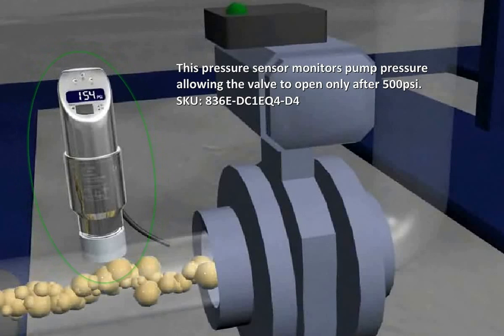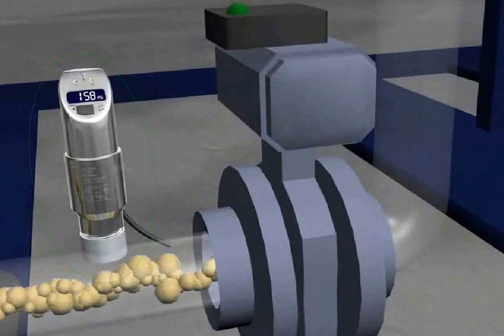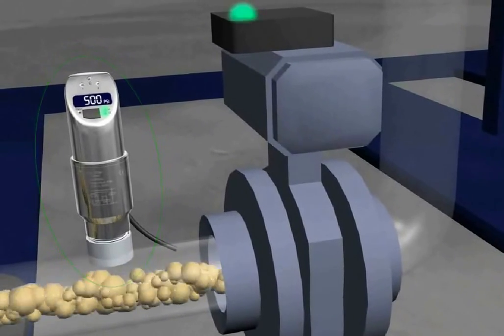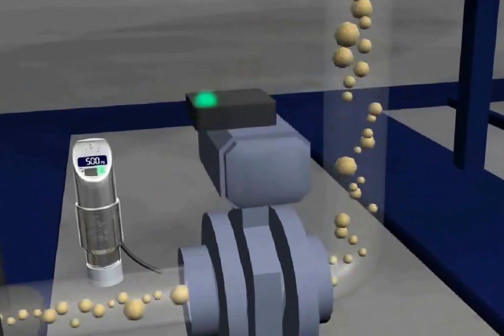Once the 500 psi pressure is reached, which is seen on the pressure sensor display and the green LED indicator, the inlet valve opens, allowing the feed water to flow into the RO pressure vessels.